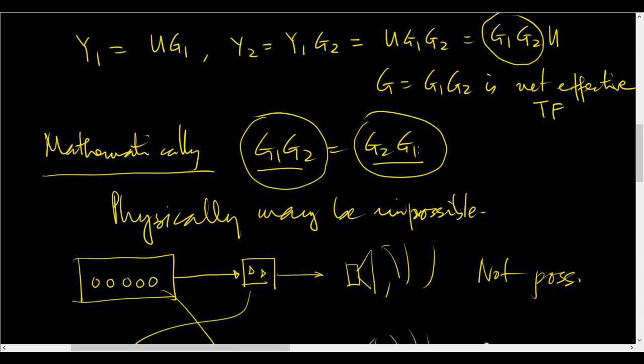So if you are a control engineer, you must remember which is the physical world with possibly big physical variables, pressures, large currents, things like that, and which is the signal processing world where everything is maybe plus minus 10 volts, plus minus 10 milliamperes. Within that you are arranging it so that you are working with the signals properly.